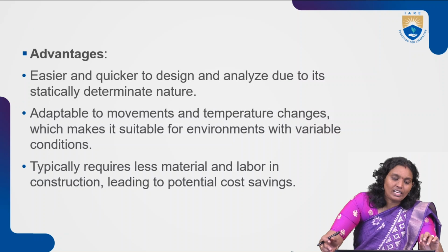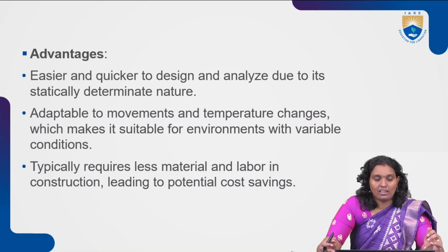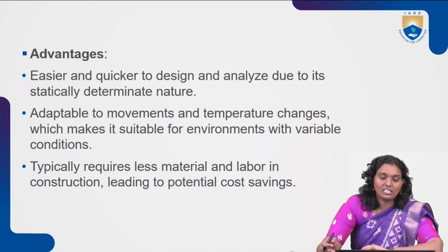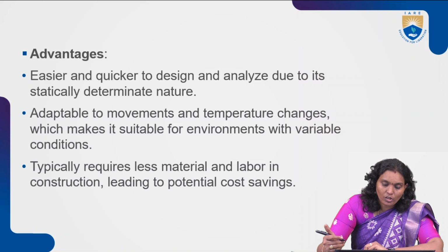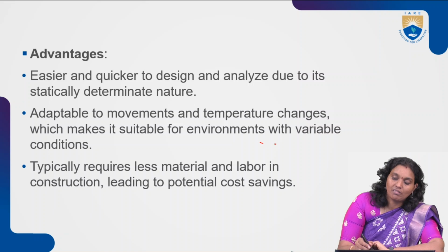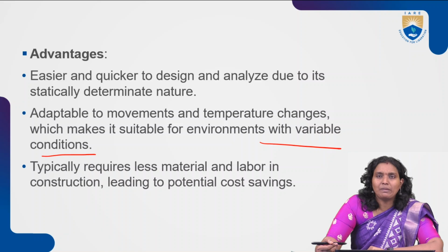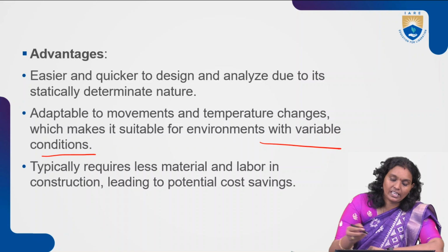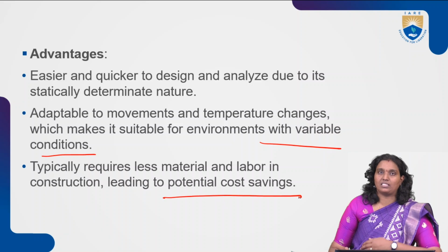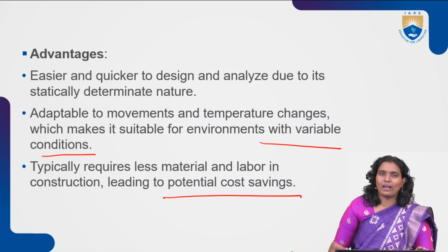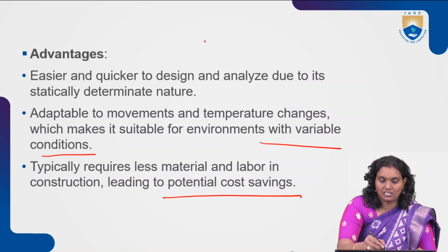And the advantages, what we understand till now based on this lecture: it is easy and quicker to design and analyze due to its statically determinate nature. Adaptability to movements and temperature changes, which makes it suitable for environments with variable conditions. It typically requires less material and labor in construction, leading to potential cost savings. These are the advantages we may observe from three-hinged arches.